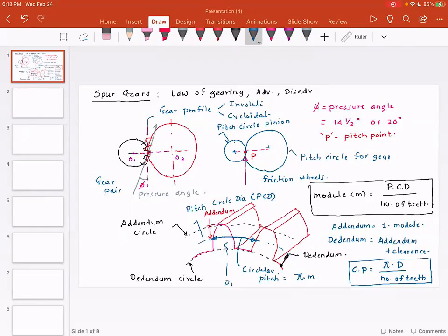And this is very important because you don't want interference. So which means when the two gears are meshing, there is some teeny tiny amount of clearance between the face of the tooth and the bottom of the gear. So that is something to keep in mind. The top part, this is called face width. Typically, we use B as face width.